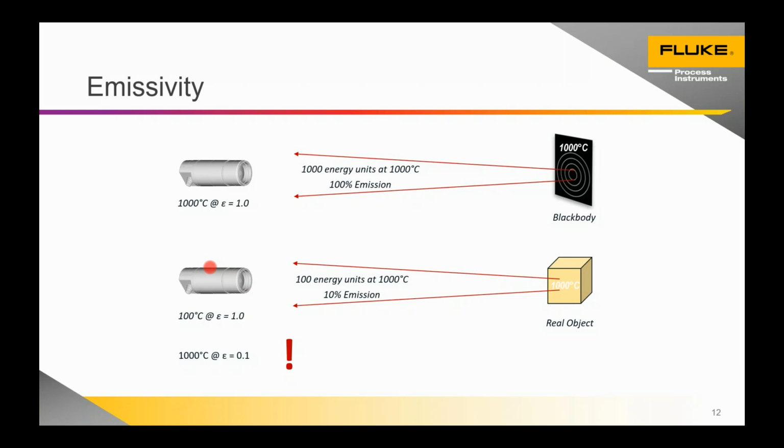If you've got an application where you're looking into a gas, generally if it's an inert gas, it's not so important. But if it's some kind of reactor, we may need to look at the absorption band of a specific gas and make sure that we specify a sensor that's away from that absorption band.